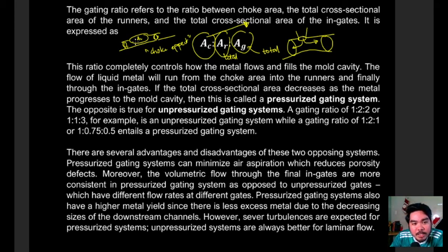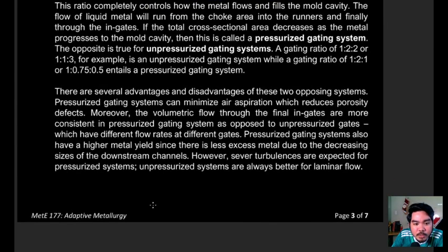If you have a pressurized system, because of the added pressure on our liquid, our gates, so if this is the runner, kunwari, it has multiple in-gates. Because there is pressure in your system, the tendency is that the flow rate from all three gates will be equal. Tama? Kasi may pressure eh.